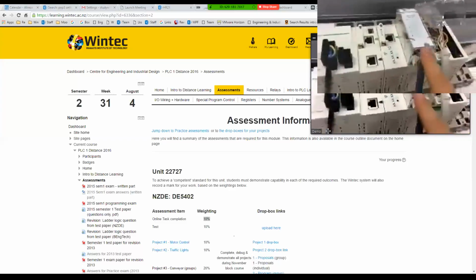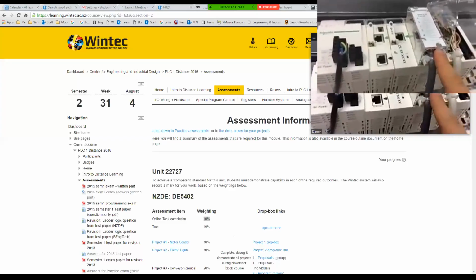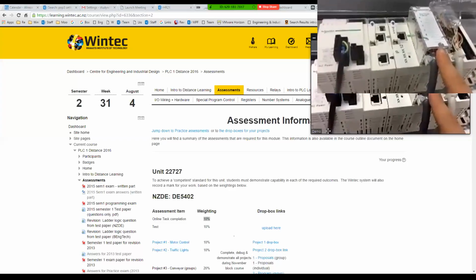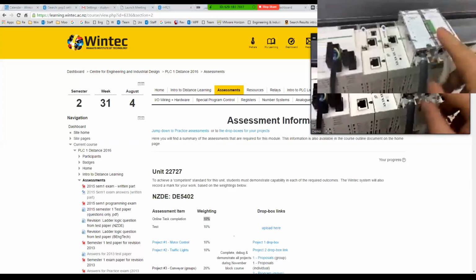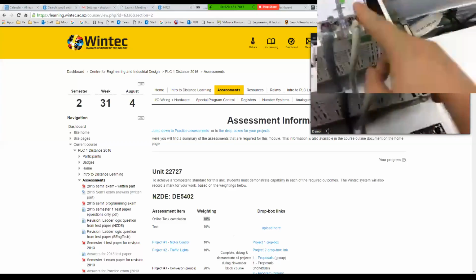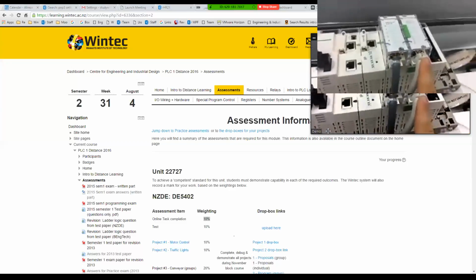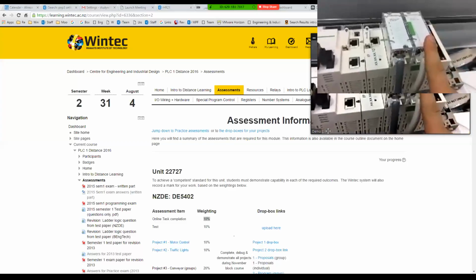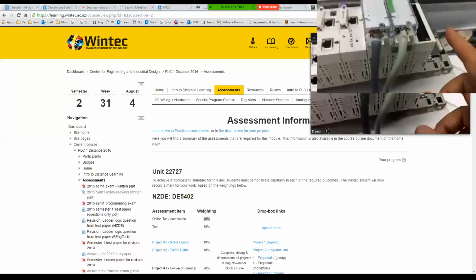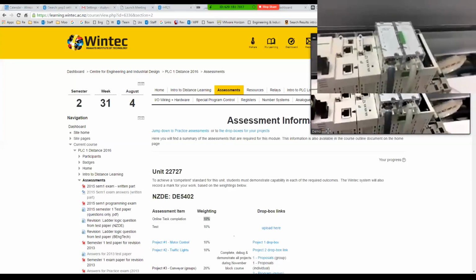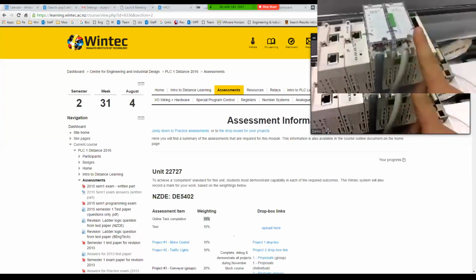It is receiving analog inputs. For example, if you have an analog signal where you measure speed or temperature or something like that, the signal can be wired here. The next one is a digital input, so a switch, push button, or a sensor or limit switch can come here. And then the next one is a digital output. For example, if you want to turn a light on or off, or turn a motor on or off, you do that right here.